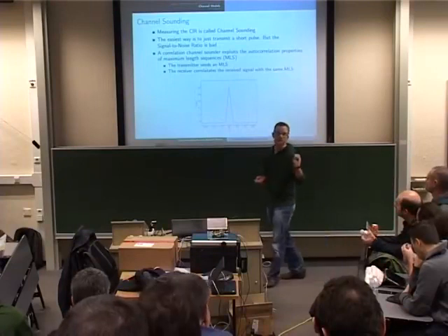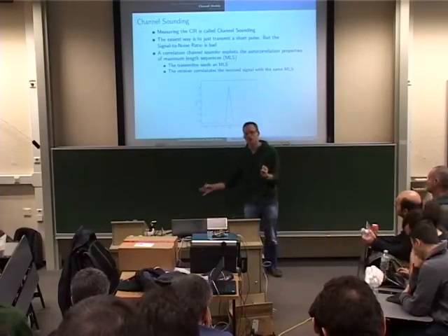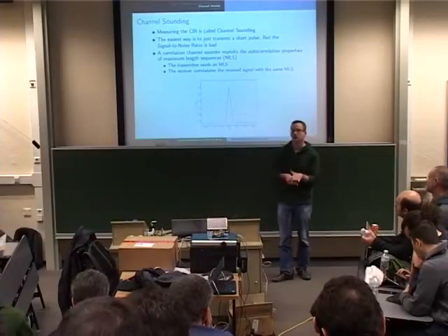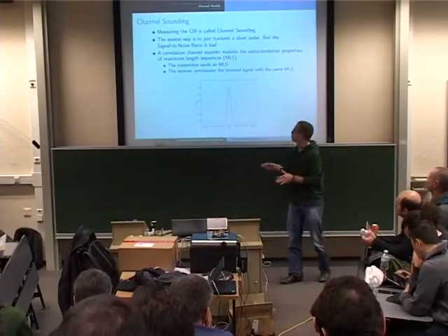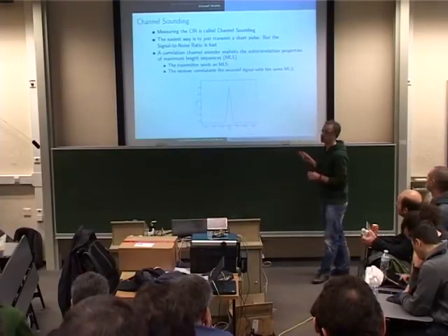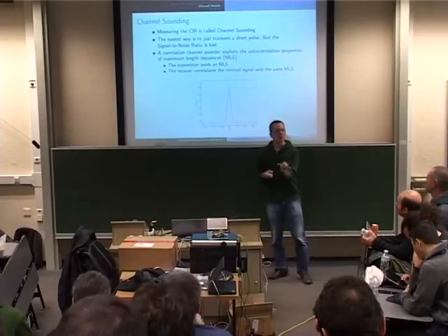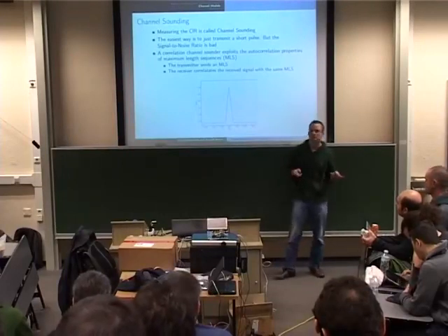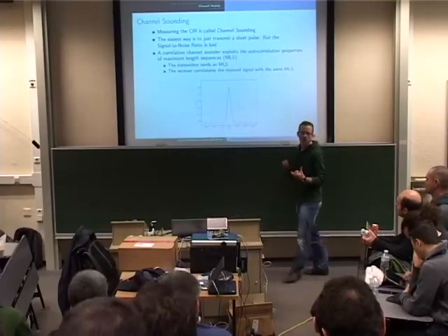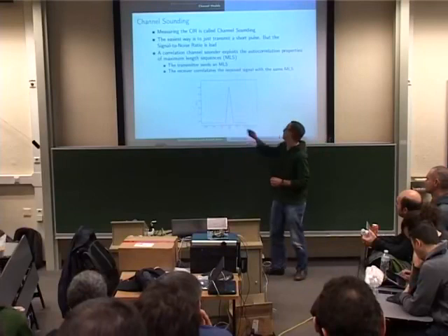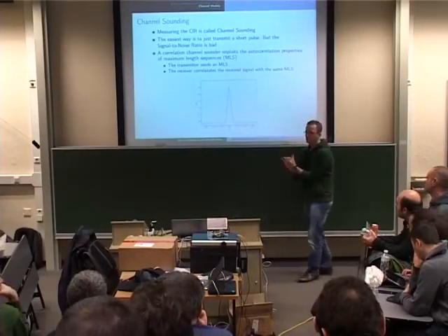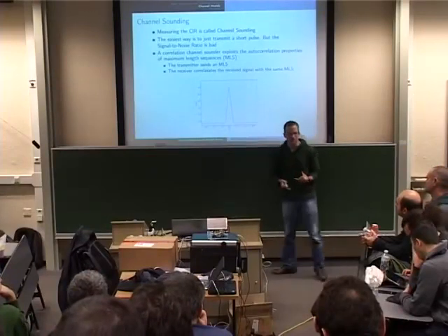The problem is, you're only transmitting very briefly and most of the time nothing, so that's not very efficient because your signal to noise ratio is very low. It's smarter to transmit all the time. So the idea is the correlation channel sounder, which transmits a sequence repeatedly, and these sequences have very nice properties. If you use the autocorrelation function on them, they've got a large peak when they are perfectly aligned, but if they're shifted a little bit, they are close to zero.